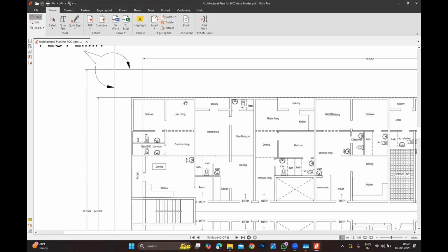The second thing, don't ever start at the plot limit. Got my point? Architects don't bother about the shoring. Most of the architects show the footprint of the retaining wall exactly at the plot limit. Then where do you place the shoring? Later what is going to happen? Everything is in addition.